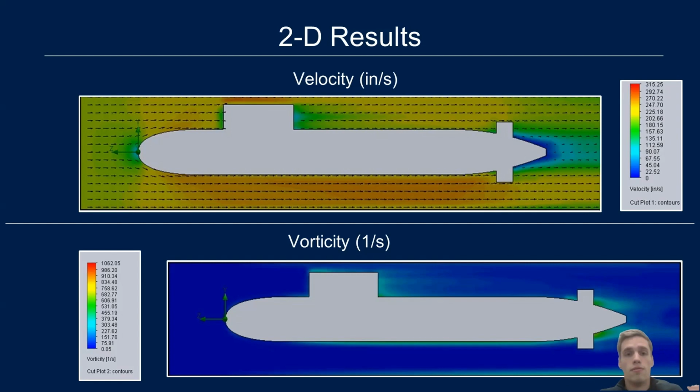So the flow is going at a certain velocity in a certain direction, the shape goes in, and the flow needs to be able to compensate for that, as well as the effect of flow separation and reconvergence. Once these flows separate around the sail and meet back, that creates some complex flows, which can result in slower velocities. Now, this is something that also goes into the second plot here, which is vorticity.